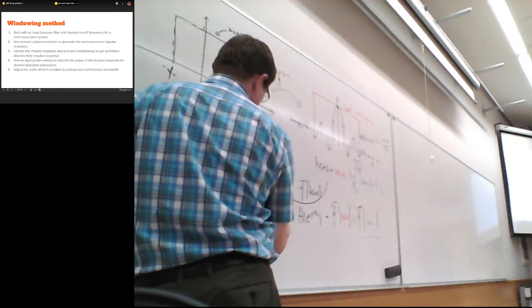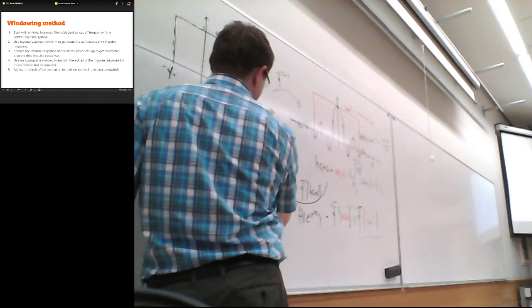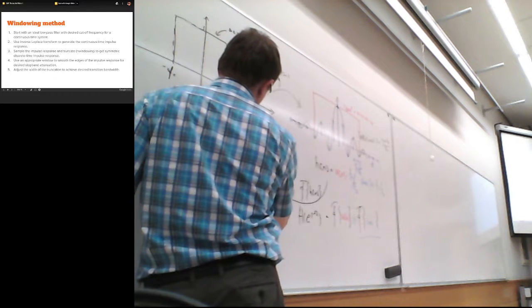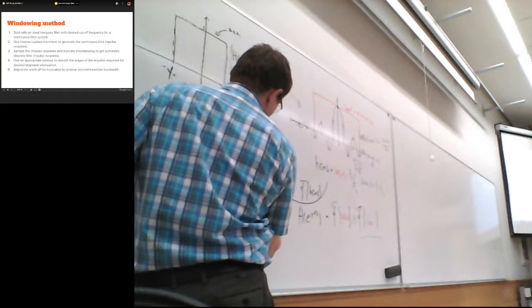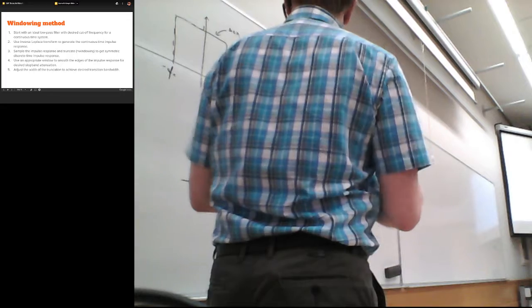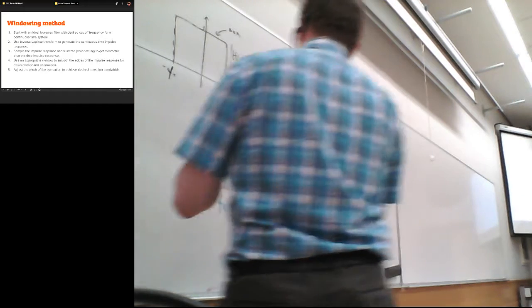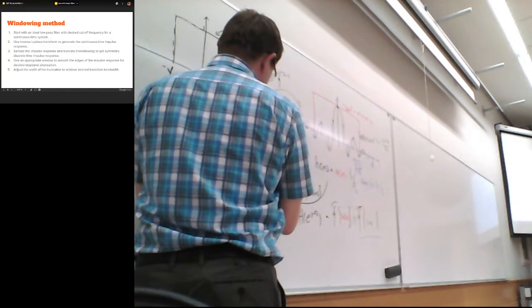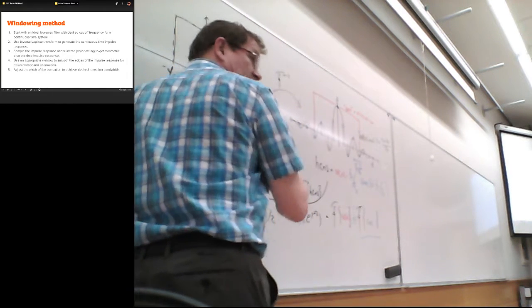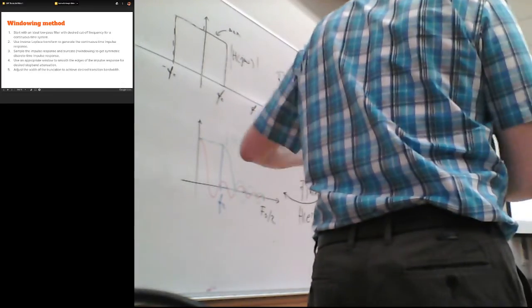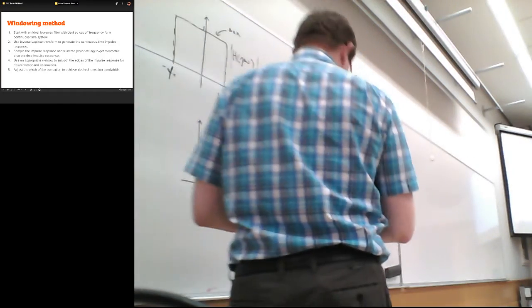Although, okay, I'll just mark this one as the, if this one is the amplitude response of H(e^jω), then actually this is the absolute value. So having the box shape window will make the transition bandwidth wider, and also it does not get all the attenuation because the sinc has every single frequency available from here to beyond.